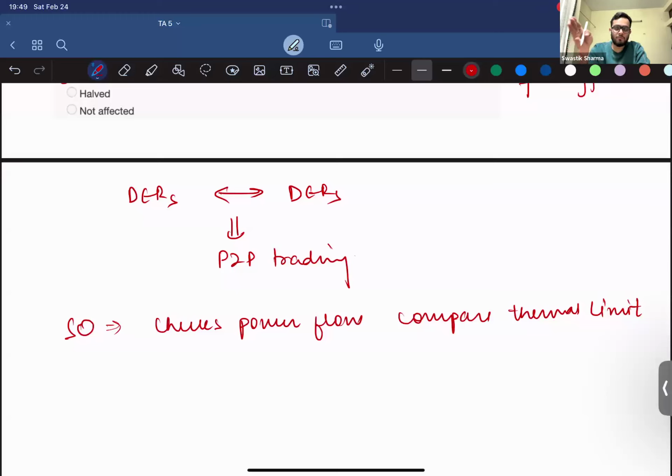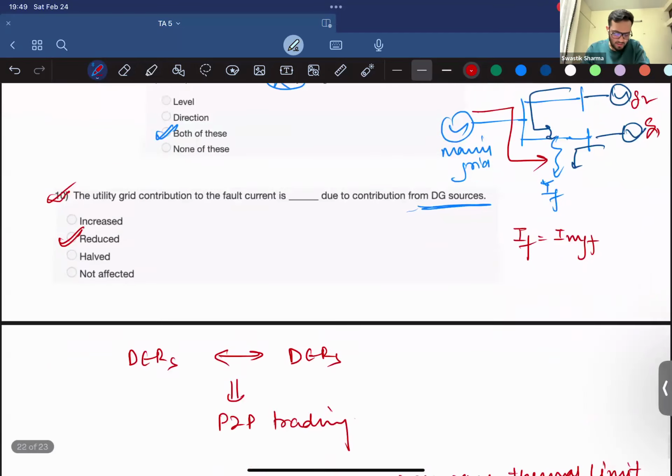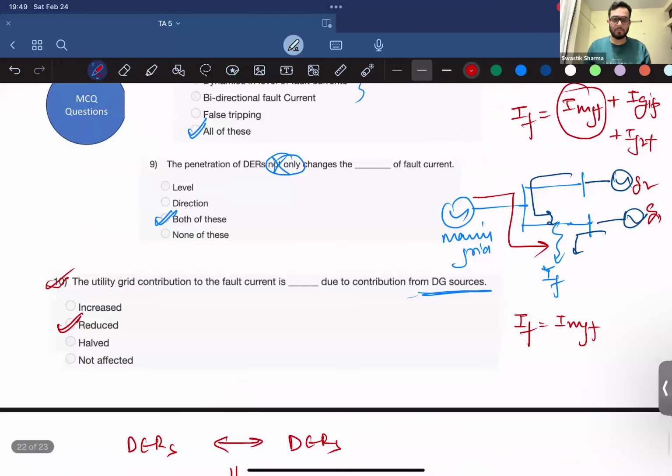To the ISO, no, because independent system operators are managing the market at the transmission side, that is generators and discoms. They don't really need to know if peer-to-peer trading is happening. It's only the business of the DSO and how it manages the resources that it has. It doesn't need to talk to the ISO to be able to manage these resources. So others, please don't focus on this question. But if someone has interest in this, I'm happy to help.